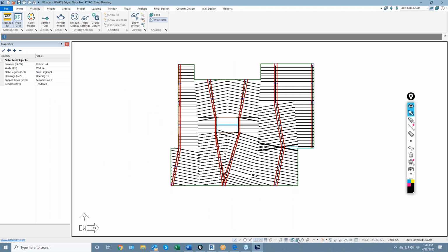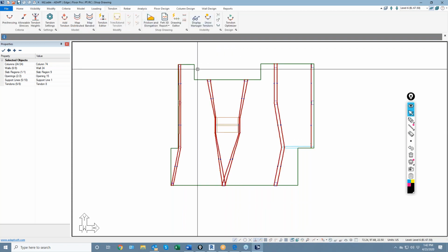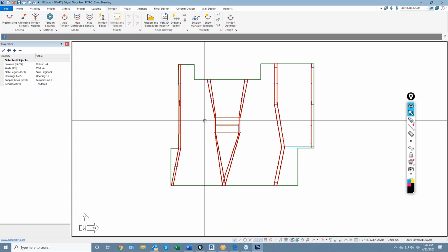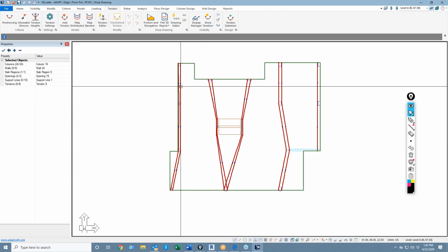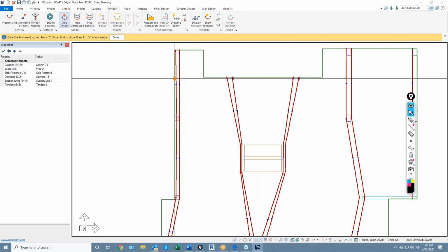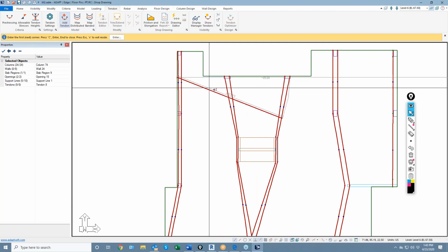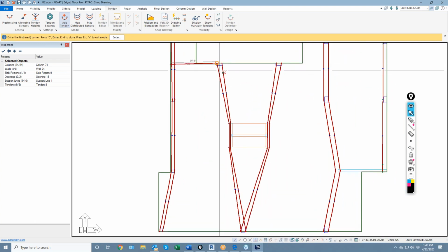And now we're going to run with the distributed cables. With the distributed cables, I'm going to turn back on my banded tendons, but I'm using them mainly as a reference to develop what I'll call the primary tendons that can then be replicated. So we're going to add a tendon, and I'll start here. I'm going to say that my tendons, for every 4 feet, I need 2 cables, okay? And that was